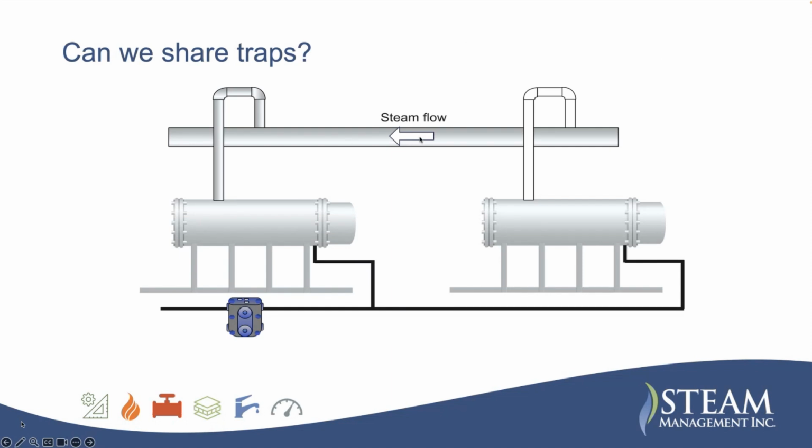Can we share steam traps? Well, you think, well, these are going to be expensive, a couple $100. I can just put both of them on here. Well, you can do that, but you don't want to. And the reason why is because if this thing is blowing steam through here and this one has a lot of condensate, it's going to be throwing that condensate back up into here and banging on the tubes and destroying it. Each steam consuming piece of equipment has to have a steam trap. So I would need one here and here.